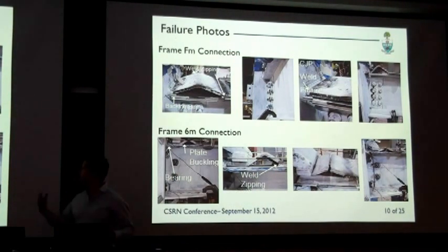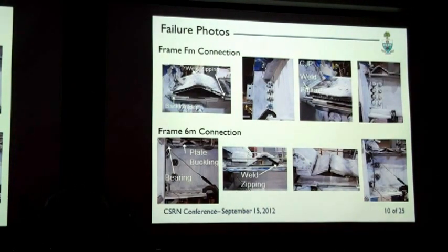And then at the end, since the top plate was basically out of the equation, the force couple was between the shear tab and the bottom cover plate, and this led to either shear tab ripping in tension or severe buckling in compression.